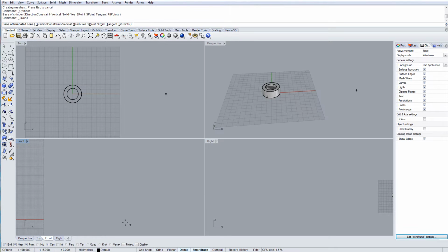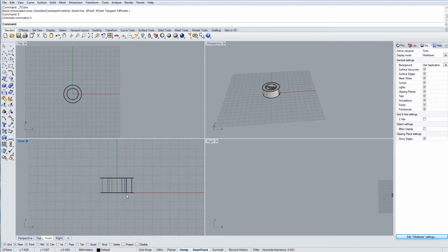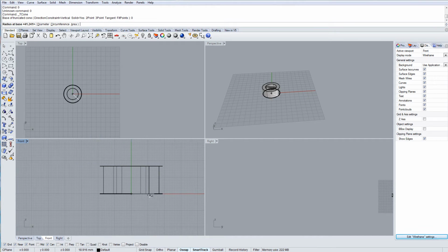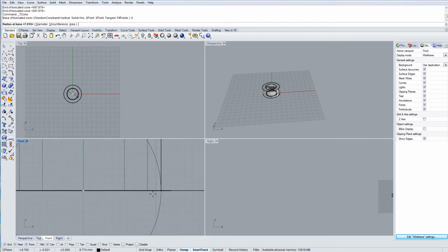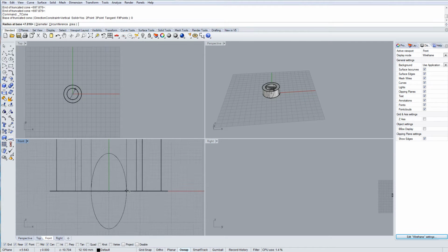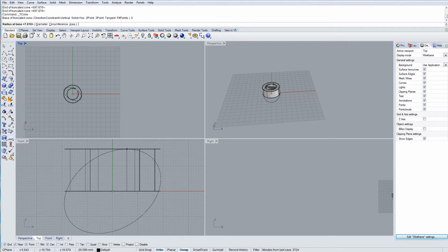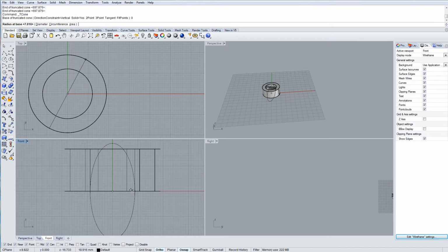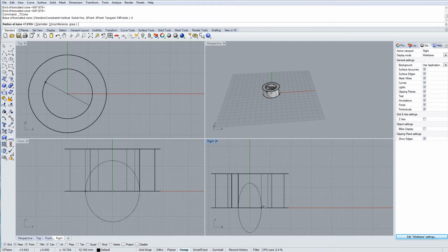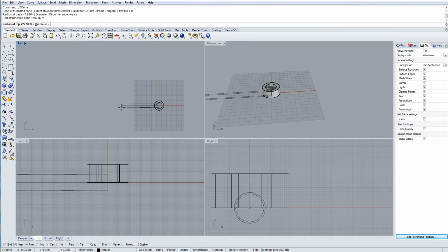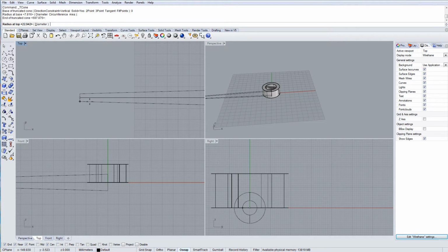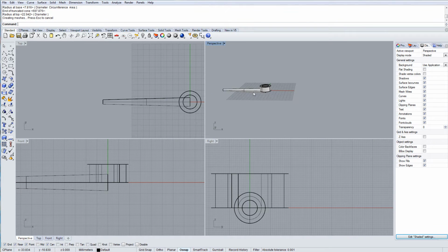And I'm going to move into the perspective, outer perspective, and I'm going to make this from the 0. So this, I'm going to make it about that high. So it's a bit smaller than the object. I'll just do that again. I'm just going to take my smart track off. So I'll make it about there. Then the outside of my cone, I'm going to make it going in this direction, and then the end of my cone I'm going to make about something like that. So I've got a truncated cone here. Don't worry about it being off center at the moment. I'll work with this in a minute.